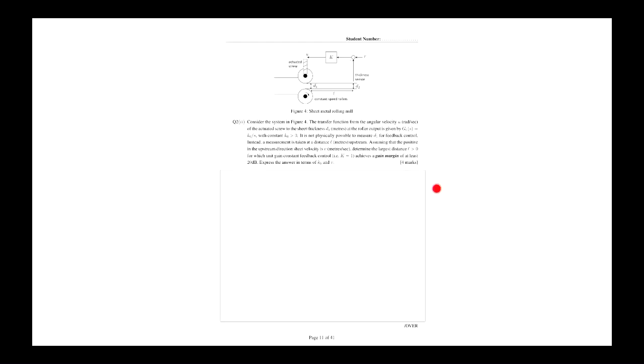So this is about phase margin, or this one's about gain margin, right? And remember, gain margin is about the frequency where the open loop transfer function has a phase of -pi radians. The gain margin is 1 over the gain of the open loop transfer function at that frequency. It's how much you'd have to scale the gain by to move the crossover frequency to where the phase is -pi, which will give you 2 closed loop poles on the imaginary axis, to make the Nyquist plot hit the -1 point.